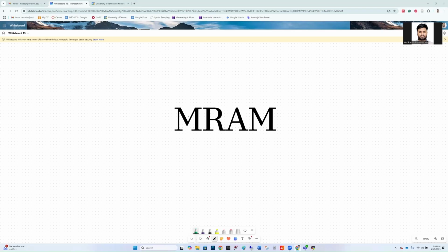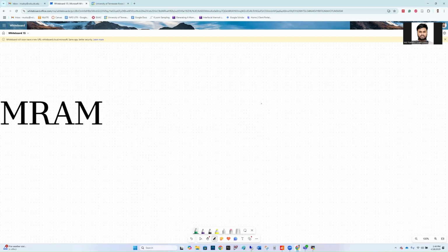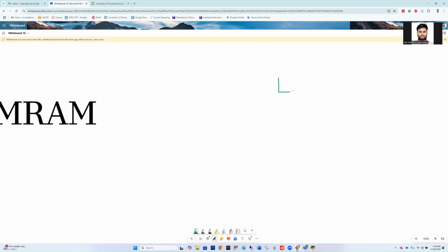So in this section of this video tutorial, we will show you how to read from an MRAM memory. So let me just draw one MRAM memory cell. This is the MTJ, and this is the bit line node, and this is one transistor. This is the gate of the transistor, and this is the source line. So we will try to read from this memory.